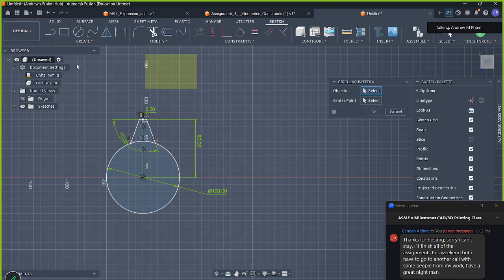So if you go any way to the left, it's yellow, right is orange. And the difference is if you highlight something going to the left, if even just a part of the geometry is inside the rectangle that you make, it'll select that.